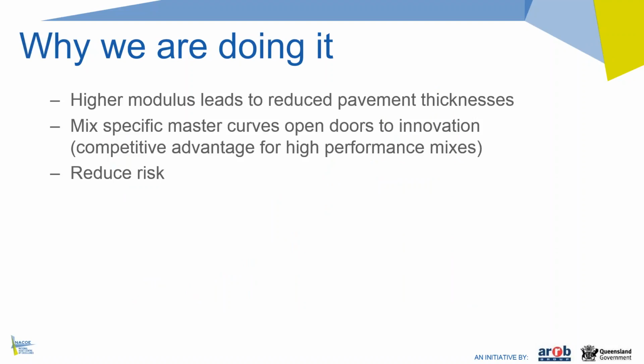Other reasons why we're doing it: these mix-specific master curves will hopefully open the doors to innovation, because they allow people who do mix designs to get the full benefit of creating mixes that have higher modulus values, especially if you combine that with higher fatigue values. So we're getting an actual competitive advantage of creating high performance mixes.